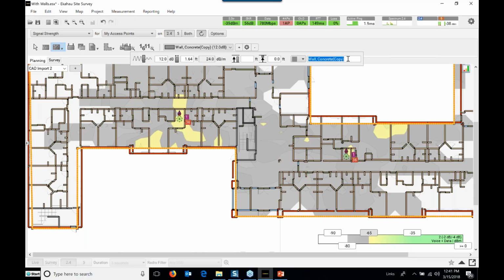I recommend starting with a blank project, building all the walls that you think you need, and then every time you need to use those walls from building to building, just open that project and do a save as, and save it as something different next time, so it's available for another use. But you can keep building as many custom walls as you want.